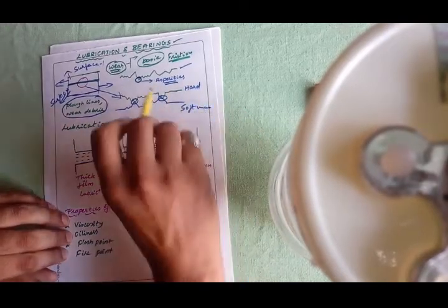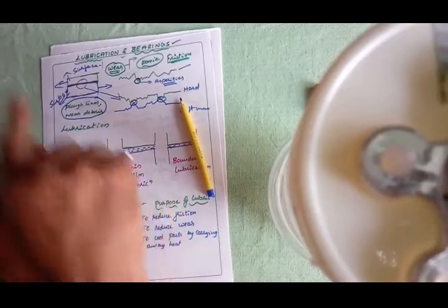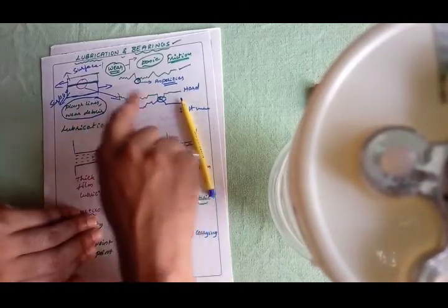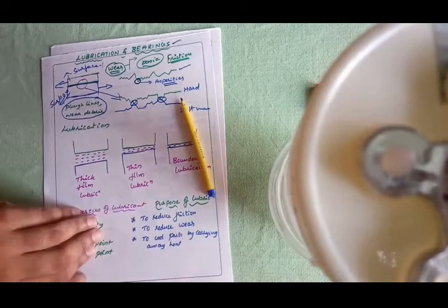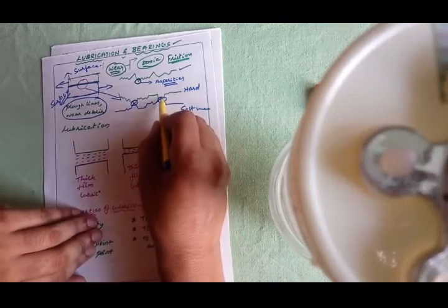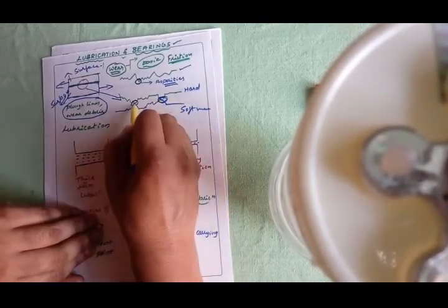Once the asperities have penetrated into the surface, and as you try to move the hard surface over the soft surface, you can see the flow lines will be formed on it. Sometimes these asperities of the hard material or the soft material will be welded.